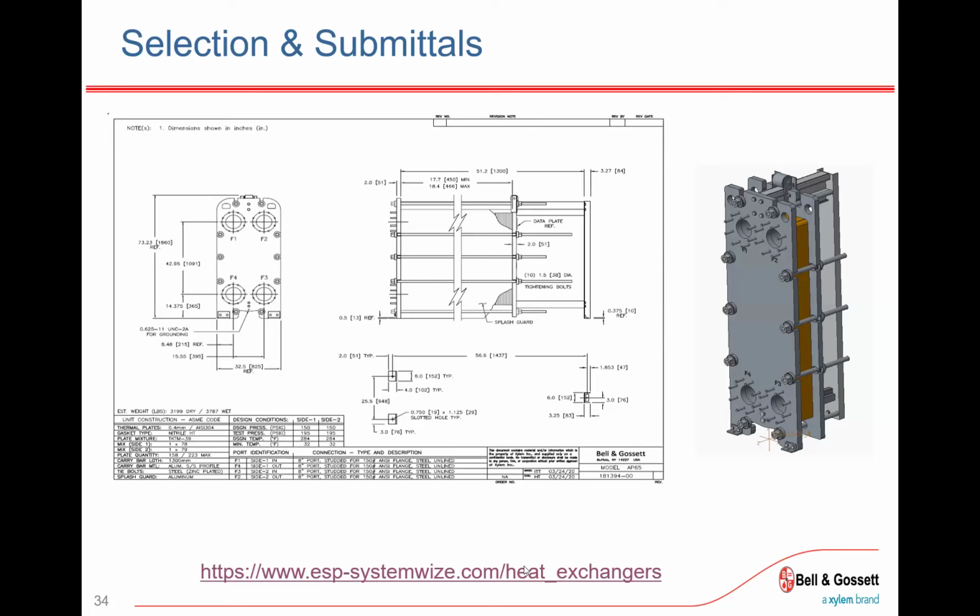Now keep in mind that if you were to change it and do, let's say, 30% glycol, and then verify input, I think it's not that drastic. But a lot of times if you see something in the tenths or hundredths on a schedule, that'll be because that's the variable they had floating. Next, just walking through it, your pressure drop default is 10 psi,